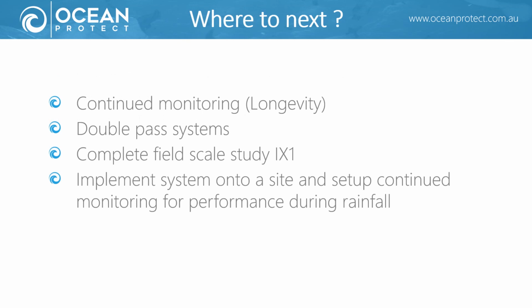Further research and evidence outside the scope of this study has indicated that linking the RFTTs in series so that the runoff water passes through 2 RFTTs will meet the target outlined in the research objectives at this average influent concentration. By linking the radial flow treatment technologies in series, this will also increase the system's ability to treat higher concentrations of PFAS utilizing the activated carbon media number 5 down to the Australian Drinking Water Guidelines.